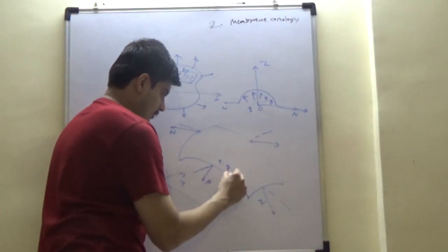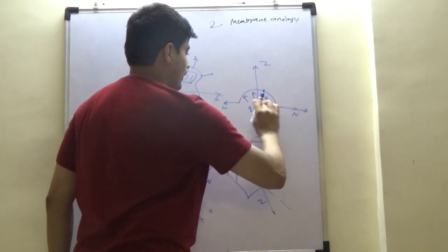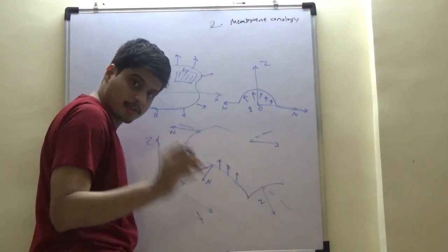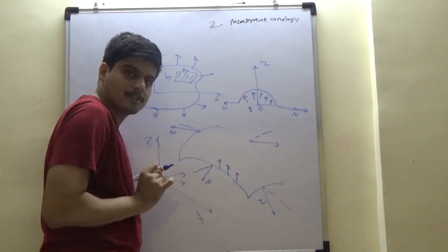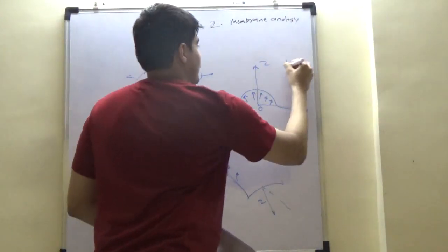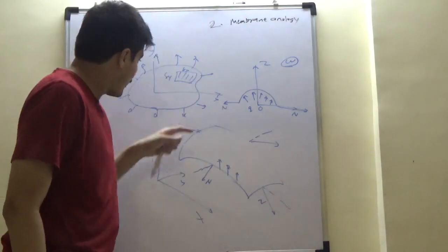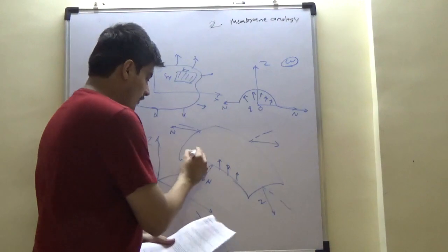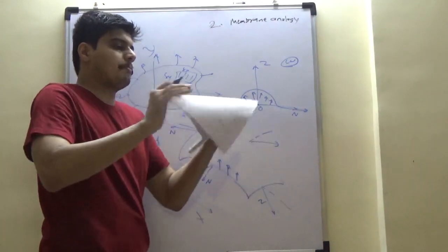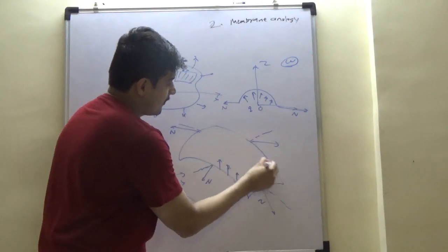And this is happening in such a way that N has to offset the projection of the component of this cube such that the load Q, which is a per unit area uniformly distributed load, is offset and balanced by this. Now, in the membrane analogy, the displacement in Z is W. We don't know whether it is warping, but it is simply the elongation in the third direction to enable resisting of this load. But we know that this Z, the bulge in the Z direction, is going to be a function of xy. It may not always be uniform and constant.